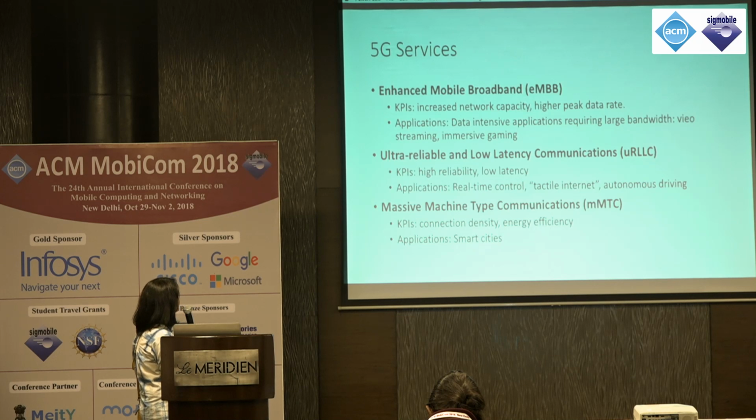The next bucket of services is what's called ultra-reliable and low-latency communications, or URLLC. The key performance indicators for that are different from eMBB: high reliability and low latency. Data rate is not the main driver here. What we want is, I don't know, 5 to 6 nines availability and extremely low latency, of the order of 1 millisecond.